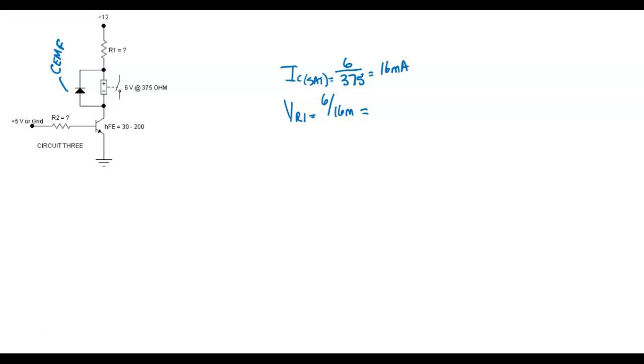All you know is that it's a 6 volt relay. I would take my ohm meter, get that relay out, put it across that sucker, and measure the ohms, right?